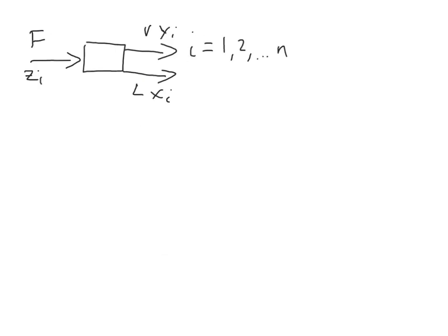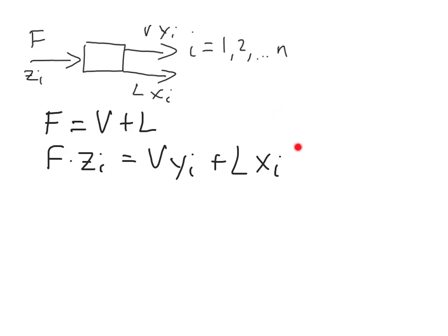So let's look at the equations that apply to this type of system. First, let's write out our material balance equations. These are our multiple material balance equations. This is the overall balance, and then we'll have various material balance equations for the different species. So before, we've only dealt with one material balance equation of this type, usually because we've only had two species. So remember that the number of species we have, minus 1, will tell us how many independent of these material balance equations we have. But we can write out various material balance equations for the different chemicals coming in and out of our flash drum.